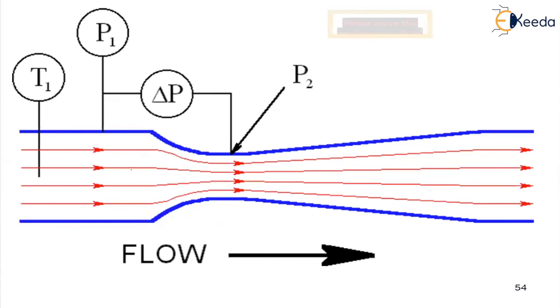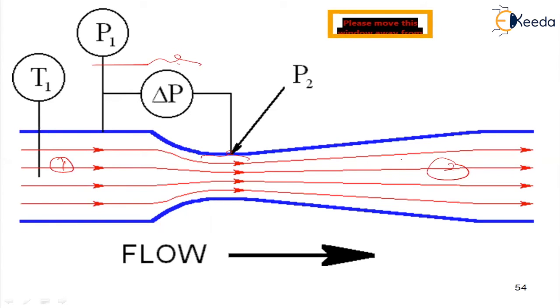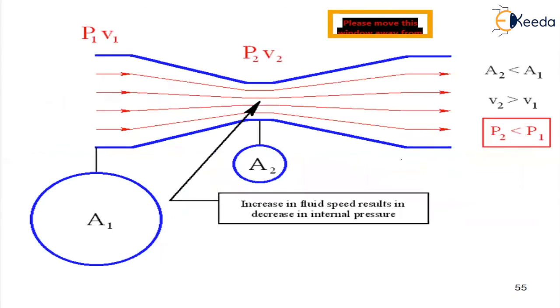Now here I'm going to take that particular Venturi tube only. Here I'm going to call this pressure delta P equal to P1 minus P2. This is the throat, my dear students, and this is the converging section, and here itself is the diverging section. Now based upon the areas, pressures and velocities, you are going to get one more formula. Here it is pretty important, my dear students. What is happening over here is pretty important.